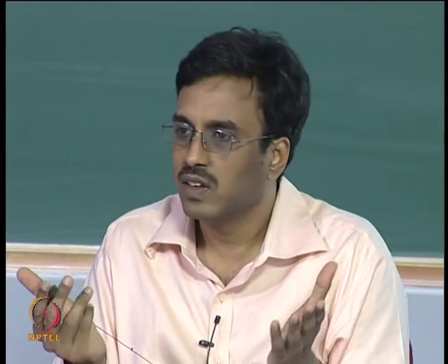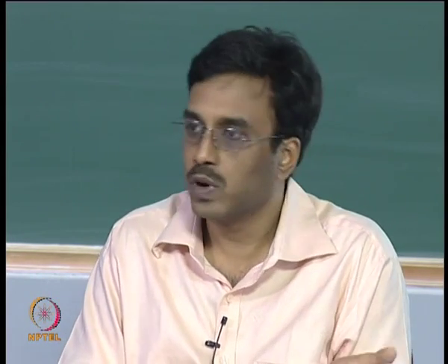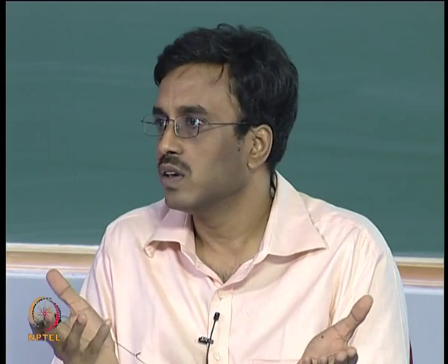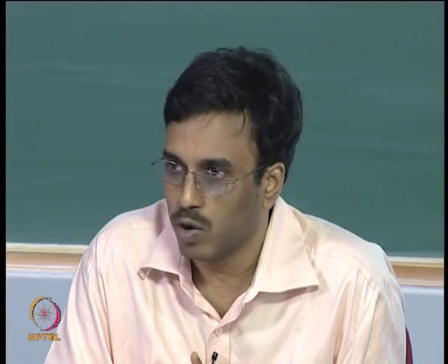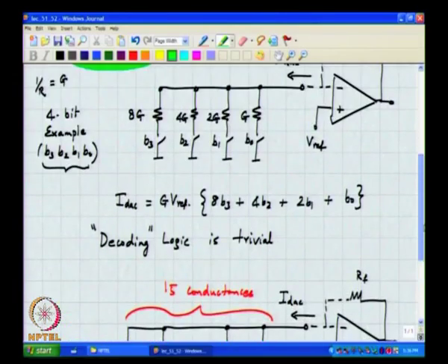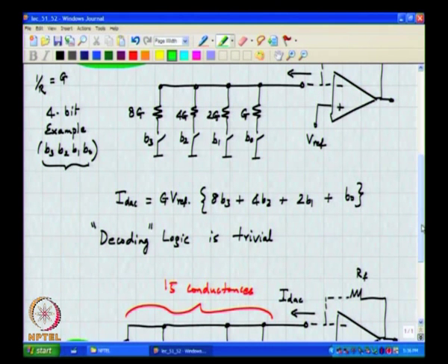Okay. So, the question is, is this a plain stupid way of doing it, or is there something that the latter solution offers which is not there in the former? You understand? One can also conceive of something between these two extremes, right. Let us say you have the MSBs controlled using this thermometer type decoding. The LSBs could be controlled by binary decoding. Is this clear?